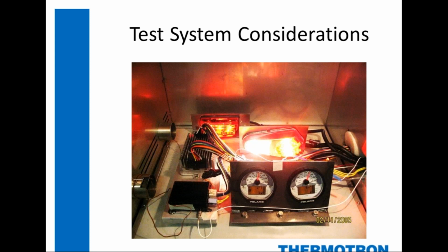Or your reliability folks might refer to those as warranty returns that are no problem found. So when it came back from the customer as a warranty, we plug it in and it works just fine. Perhaps if you stress it in an environment, you can then reproduce that failure. And I'll tell you, on an environmental chamber, there's a pretty powerful controller, and a lot of the advances that have happened over the last decade have to do with this exact same thing: monitoring products, supplying voltage to them, turning products on and off, and then detecting those very short duration intermittent failures.